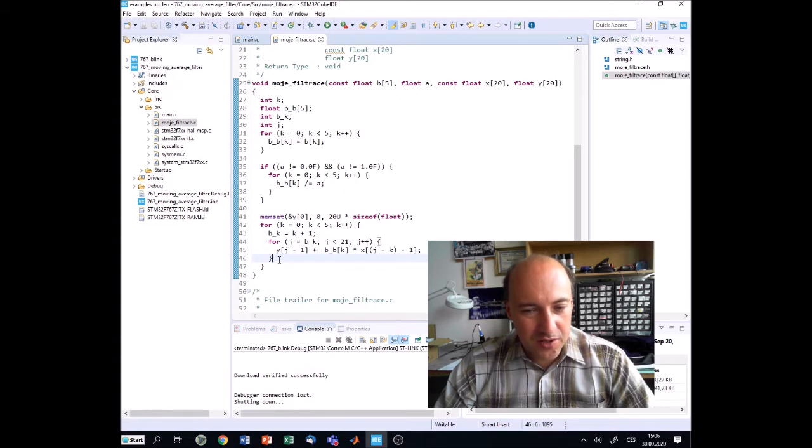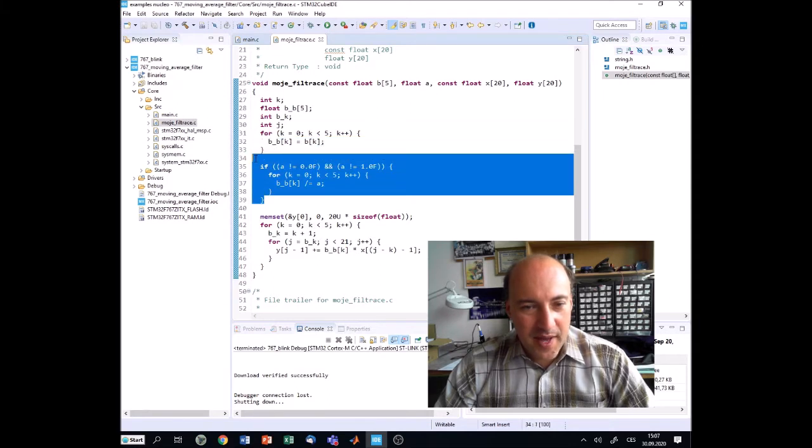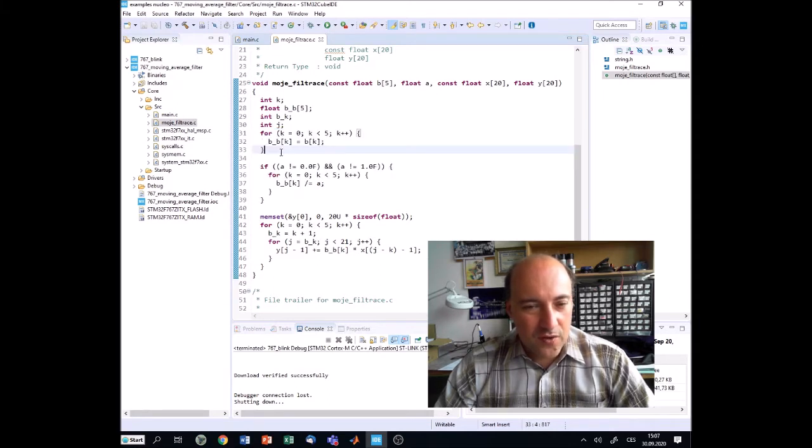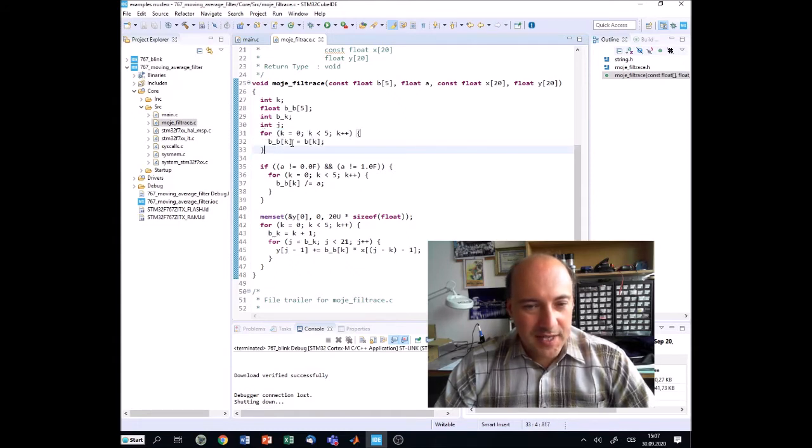So this is the actual filter algorithm, and what is actually here depends on the settings of your compiler. Now I have kept this as well. I have kept this local copy for the coefficients of the filter. We could modify this, but I just want to keep this right now because this should be the original file that we have from MATLAB. So this is the C file.